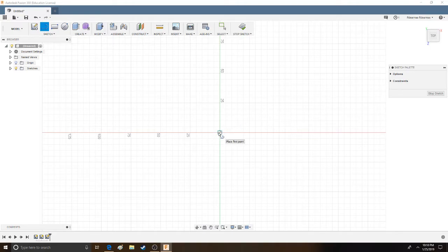All right, so select the center point. The center point should be right in the middle. It should have that logo on it. And once you've done that, this is attached to it. So this right here is the line that you've created from the normal sketch tool. So just by selecting the center point, this gets attached to your cursor. The two numbers and the degrees you don't need to worry about, since there's a grid on the back of the Create Sketch workspace.